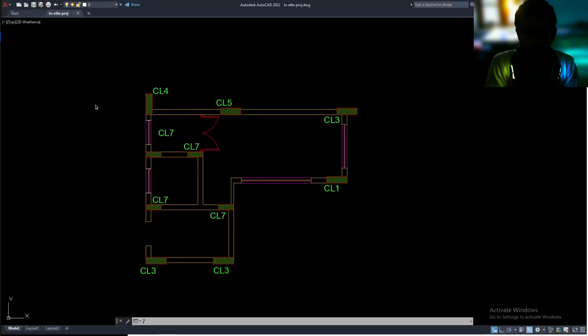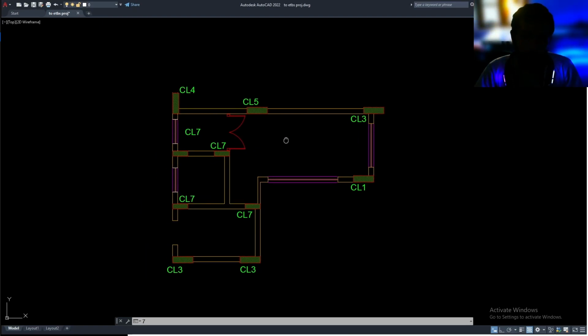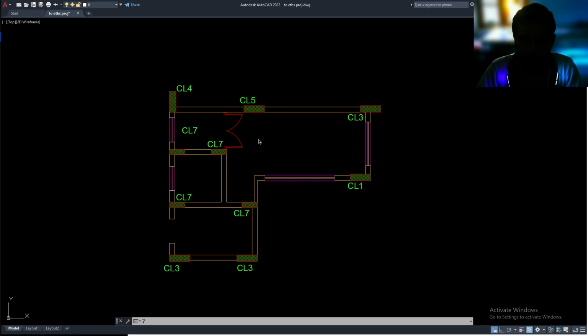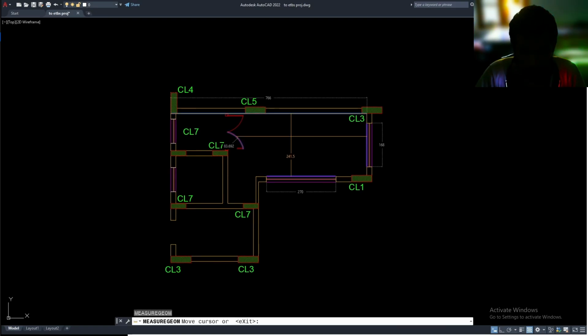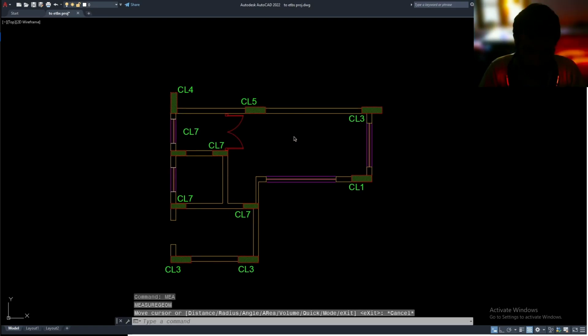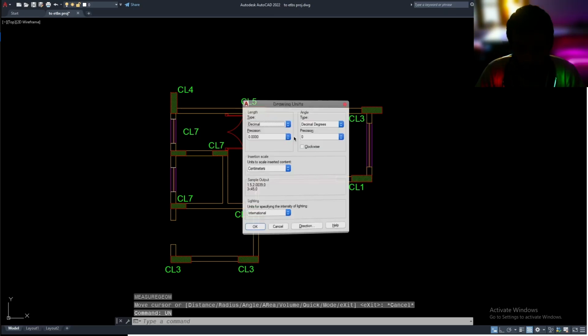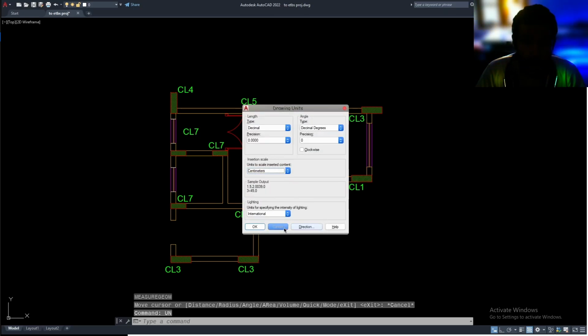This is by far the quickest method of exporting a CAD file right into ETABS using the structural objects method. So first, let's create certain layers for beam, column, and slabs here. Before doing everything, I like to check the units. It's in centimeter, and I like to convey this into AutoCAD by making use of this option here.